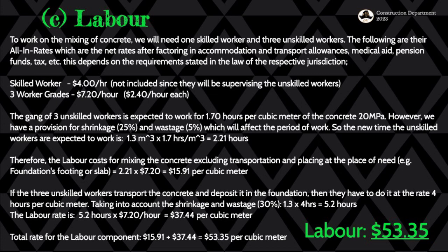And then if the 3 unskilled workers transport the concrete and deposit it to the foundation, then they have to do it at the rate of 4 hours per cubic meter. That's the constant that we are going to use for foundation in this example, but if it's slab, it depends. It means that they're going to need more time. And if it's maybe for lintel, which is above the door or above the window, it also needs its own pricing and its own time.